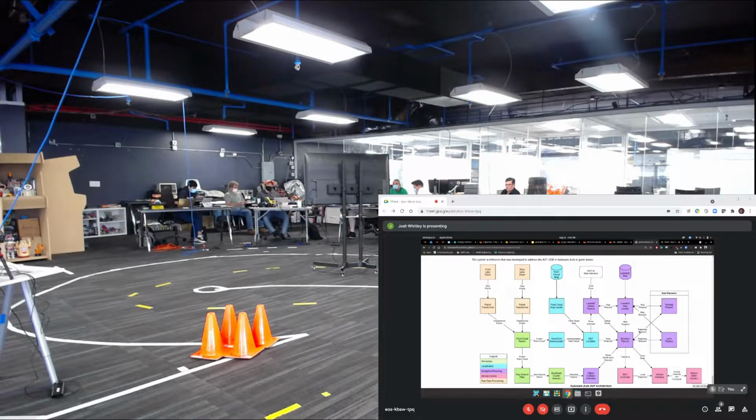So the behavior planner would call the subplanners, get waypoints from them, and then aggregate those waypoints into a full path of waypoints from beginning to end. Then it uses the pose estimate to figure out where we currently are along that list of waypoints, and passes a small look-ahead distance of waypoints to the vehicle controller. In this case, we were using an MPC controller.